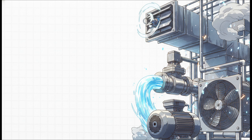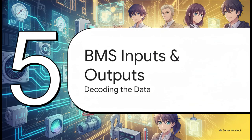We've got motorized control valves sliding open or closed to push chilled or hot water into coils. Then there are VFDs, variable frequency drives, that dynamically ramp up or dial down the speed of giant electric motors. And of course, relays and contactors, snapping shut with a loud clack to fire up huge pumps and exhaust fans. Which brings us to Section 5, BMS inputs and outputs, decoding the data.